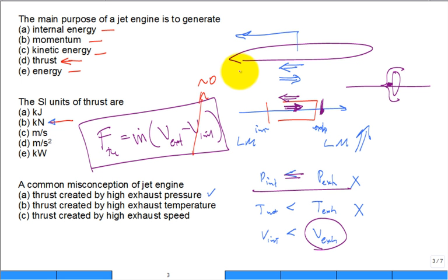But once the pilot has it up and it's cruising at 32,000 feet, at so many miles per hour, it could be easily cruising at 0.5 Mach or 0.8 Mach. That's actually a good cruising speed, 0.8 Mach, which means that the inlet air to that engine is not stagnant anymore. So the same engine in a different condition could have that term negligible on the inlet or not negligible on the inlet. But this is the best equation.